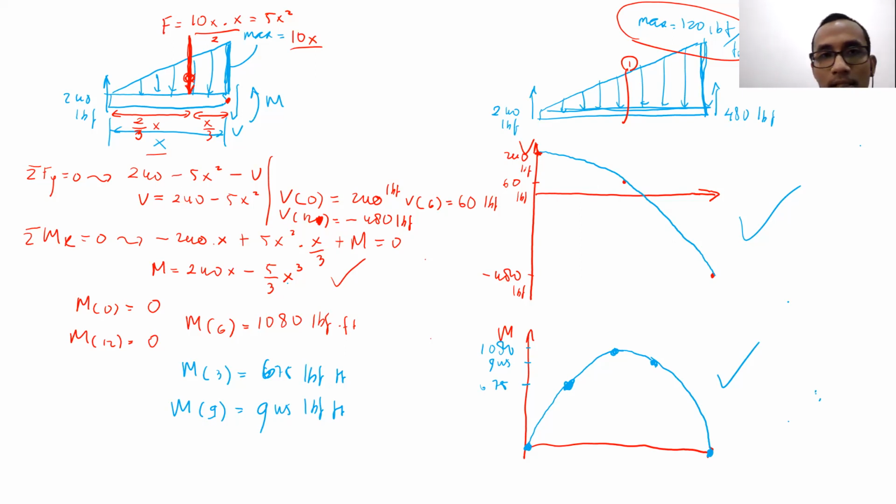Yes. So basically, just now I'm asking Darian, if we want to find out the distributed force, the maximum distributed force at a certain location, what is the equation? The easiest equation is based on the maximum for the whole length, which is 120 lbf per feet. So your W equation, W is the distributed force, is supposed to follow the maximum.